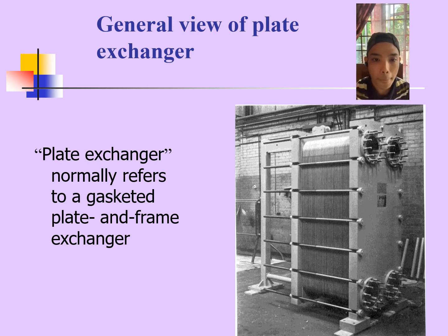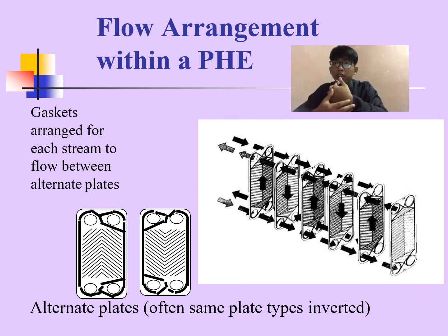Thank you. This slide shows the flow arrangement within a PHE. Please look at the photos. These are alternate plates, often the same plate type inverted. The gaskets are arranged for each stream to flow between alternate plates. Now we go to the next slide.